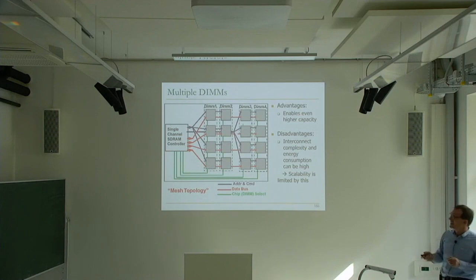A bit weird meaning that it was a daisy chain. Does anybody know what a daisy chain is? OK, the daisy chain is basically you have a controller. It's connected to the first DIMM. And that DIMM is connected to the next DIMM. That DIMM is connected to the next DIMM, next DIMM, and so on.